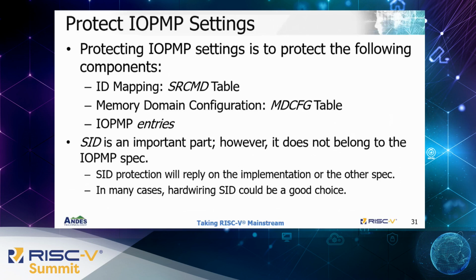Even though SIDs are very important for an IOPMP-based system, they don't belong to the IOPMP itself. Their protection involves the bus master's design. In the current stage, SID protection is implementation dependent. In many cases, it can even be hardwired. If it is not, allow the change only at boot time unless you have another protection mechanism.